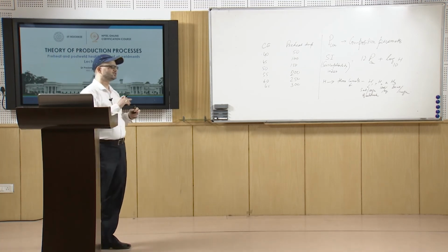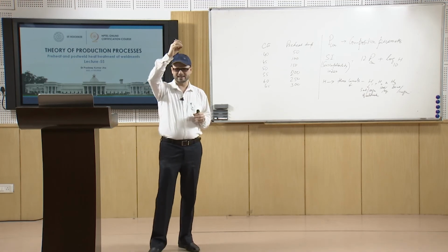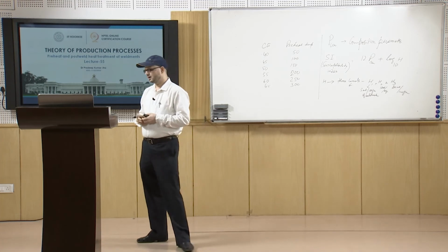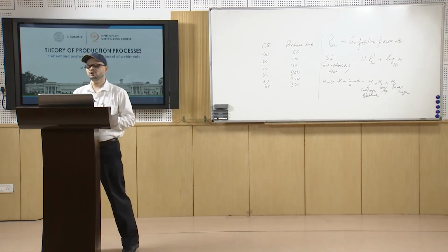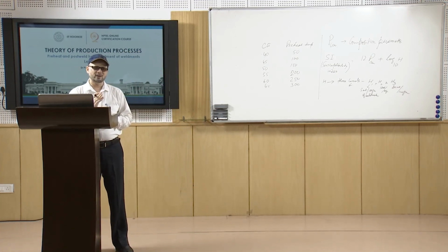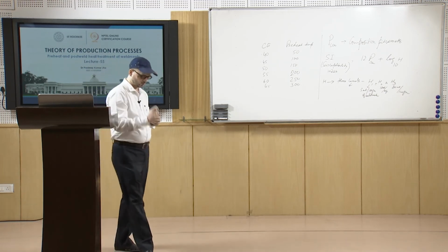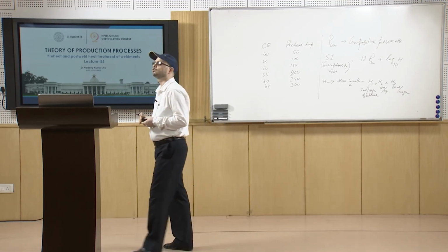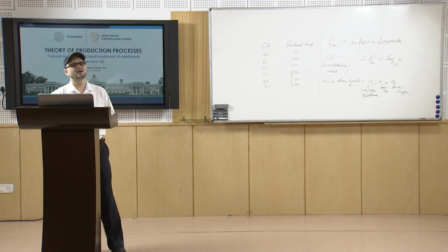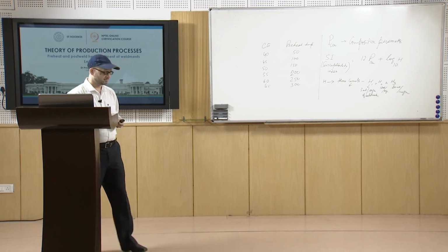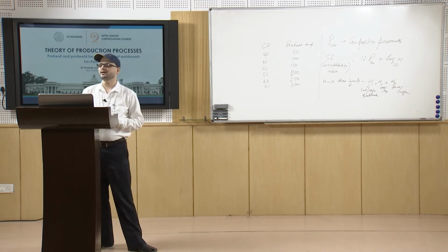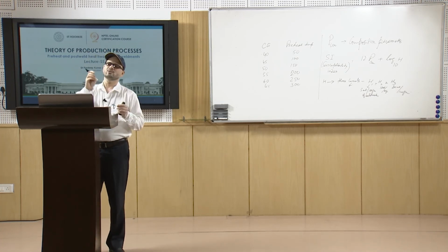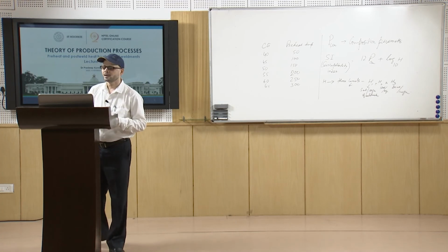When we finish the welding, for steels, you do not go to room temperature; rather, you further heat to a temperature larger than the martensite finish temperature for heat treatable low alloy steels, hold for some time and then cool.